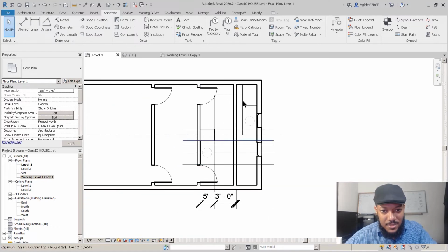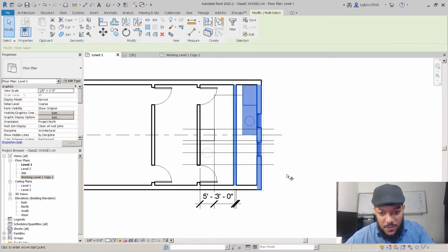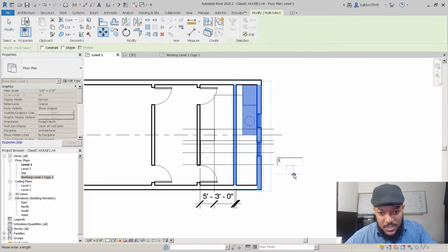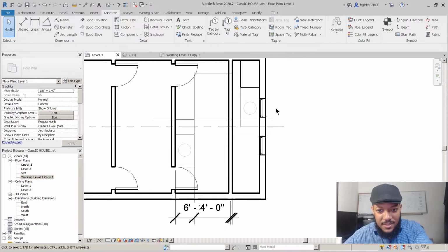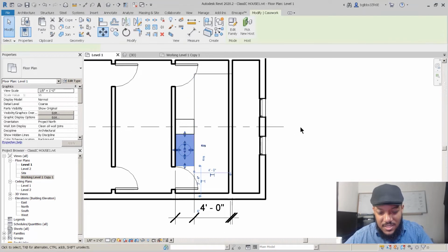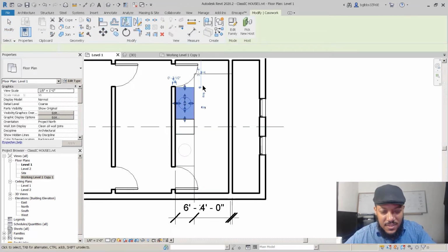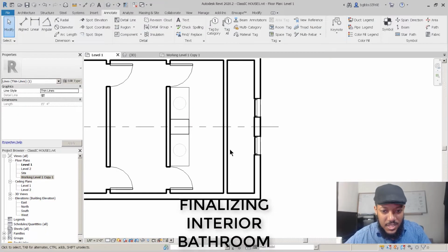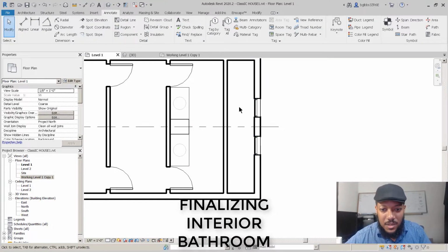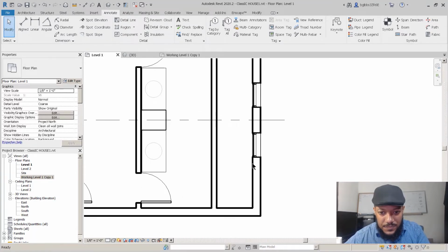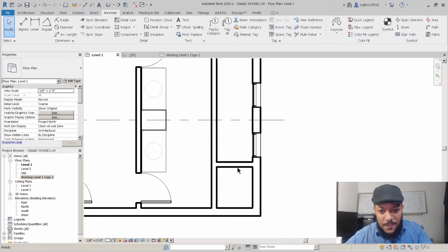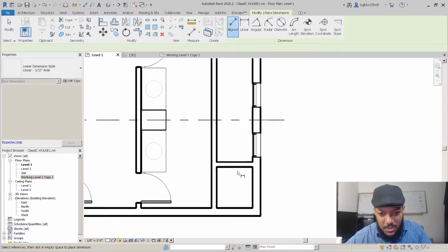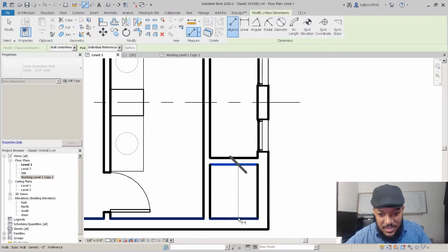And because that does seem a little bit cramped, we're going to give 4 feet. I'm going to come out 1 more foot so people have enough space. And since we figured out a lot of this stuff, we'll take out those construction lines. And now we're going to add some of the information that would help us for our walls. So right now we're going to make a 5-foot shower and a 5-foot toilet. And we're going to press Control so we can hit the edge.